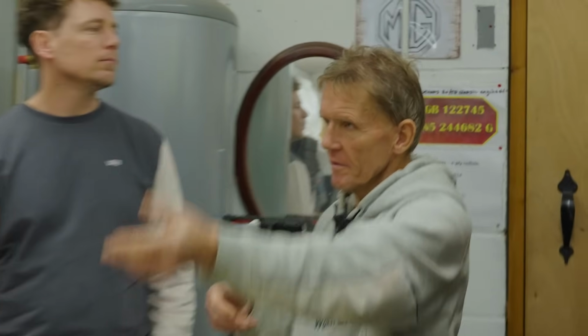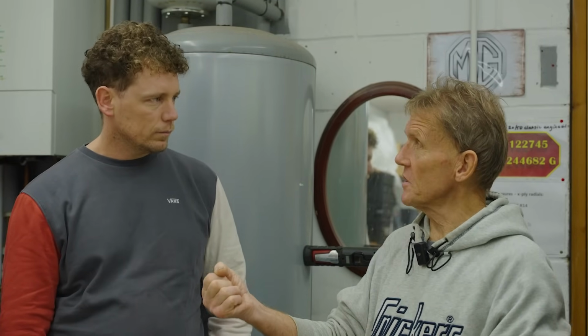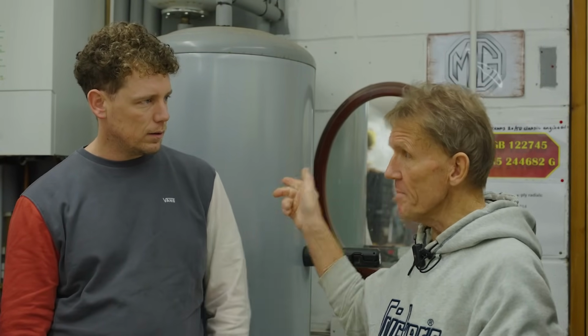I'm just going to ask you one question, because although I can understand that you get the thermal losses from the building materials, what do you do about air changes? Because they're going to be so variable. Now, with a boiler, it modulates. Most combi boilers have got more than enough capacity to deal with anybody's heating. But with a heat pump, you've got to get it right. We're always told you've got to get it right. So the air changes, to me, in many cases, are an unknown quantity.